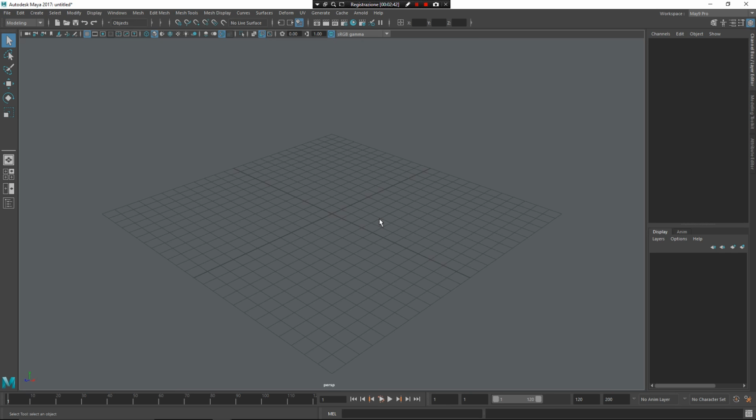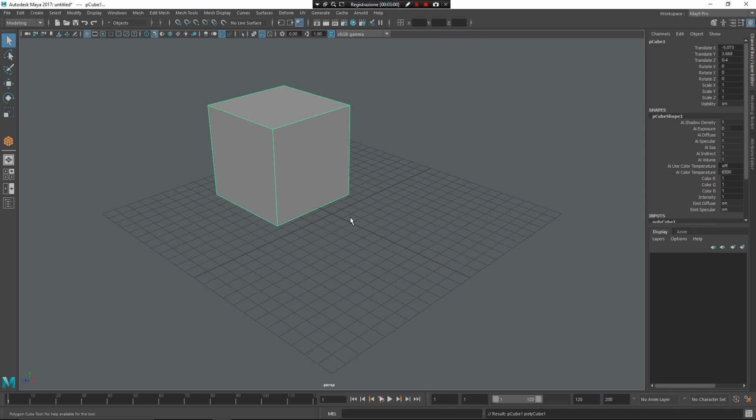So I'm going to try to create an object. Press Z, go to North. Now I want to create a cube. Remove my finger from the middle mouse button, the scroll wheel. Press Shift to make a perfect cube. Shift and drag with the left mouse button. Press Z, middle mouse button again, and now I want to create another cube. In this case, I don't want to use Shift for an interactive draw, not a regular cube.